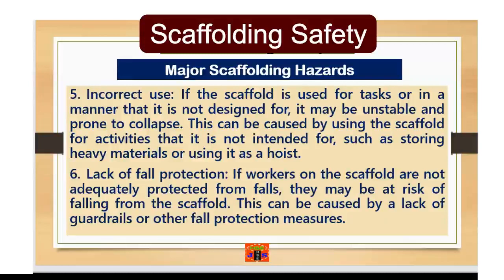Hazard number six, lack of fall protection. If workers on the scaffold are not adequately protected from falls, they may be at risk of falling from the scaffold. This can be caused by a lack of guardrails or other fall protection measures.